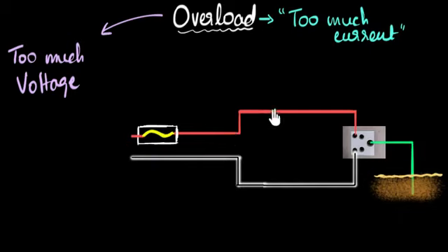We've already seen that the typical voltage between the live wire and the neutral wire in India is about 220 volts. That's supposed to be the voltage, and all your devices are designed to work on that voltage. However, sometimes, maybe there is a lightning strike, or a huge magnetic field comes in, or some static electricity, and due to something, voltage can suddenly increase. We call that a voltage spike. If the voltage increases in the circuit, immediately the current in the circuit will start increasing. So that's one of the ways in which overload can happen. And again, a fuse protects us from such voltage surges.